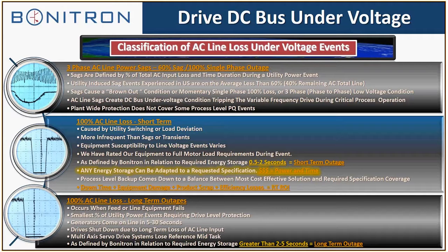But we can use ultra caps between 2 and 5 seconds if we use the heavy duty or battery booster, which we just started doing this last year, and it's working out really well. We've had a couple applications with that. But anything greater than 5 seconds, we still use valve-regulated lead-acid batteries. There's nothing special about the batteries. You have to make sure it's going to provide the correct amount of amps.